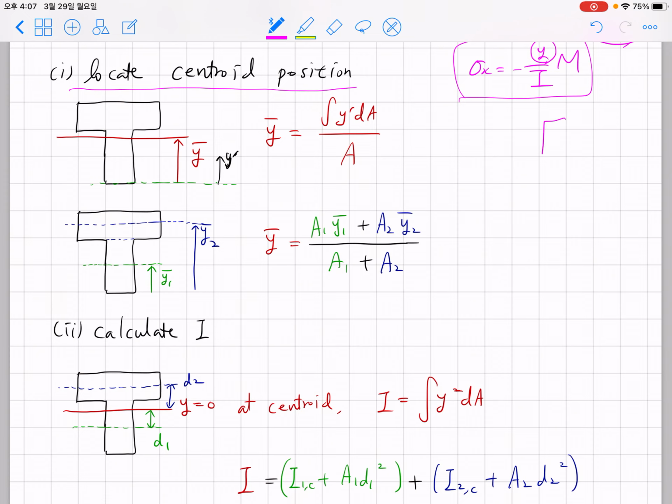If we have a rectangular cross section, it's really easy to locate the centroid. But when we have a more complex geometry for the cross-sectional domain, we have to rely on the definition. What we have realized is that the definition of centroid is mathematically analogous to the definition of center of mass, and regarding the center of mass, we have intuition. If we can decompose the cross section into two parts, and identify the centroid of each part relatively easily, we can use this expression.